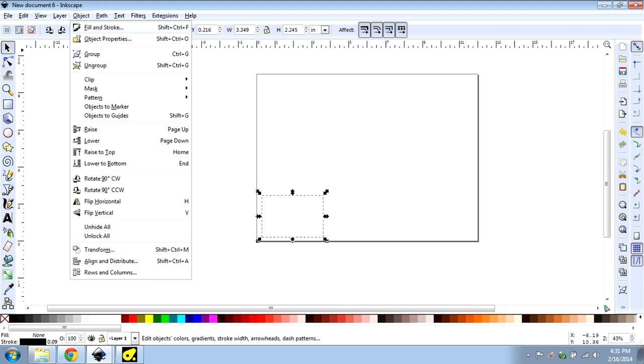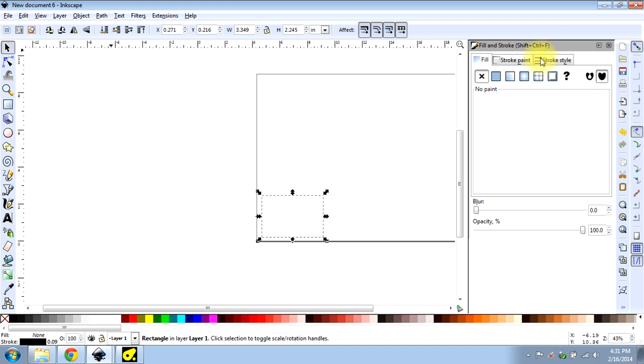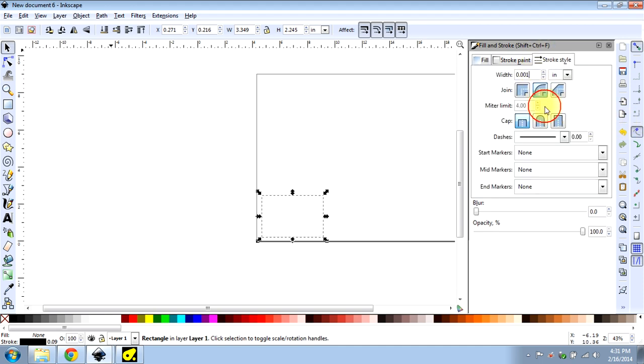I'll show you exactly what that line is. I'll go here to Fill and Stroke, and you'll notice this is a 1,000th of an inch line, 0.001, and that is what you want to work in. Whenever you're designing anything, the CNC software, the laser cutter software, et cetera, is going to see this hairline of 0.001 inches, or I don't know, 0.1 metric. It's really small, right?